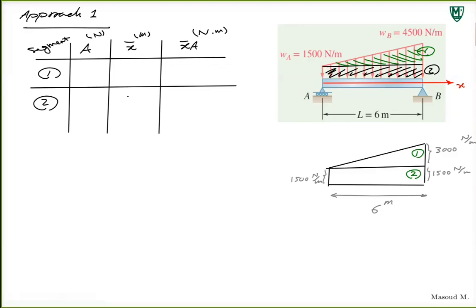So the area of each segment is basically a force, which shows the magnitude of the equivalent concentrated load. Once you find the area for this triangle, that area represents the force you could put at the centroid of this triangle as the point load. So that's some kind of force. Let me continue this, maybe it makes more sense.